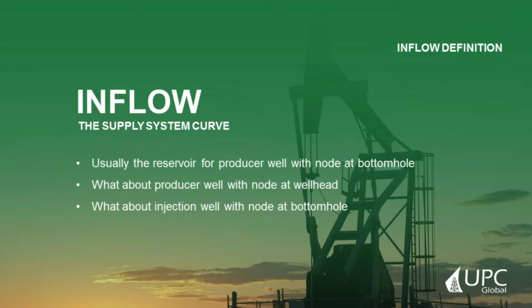What about an injection well with a node at the bottom hole? We can use this, and then inflow, as we will see later, will be the pumping system at the surface and the tubing, and the outflow will be the reservoir when the node is at the bottom.